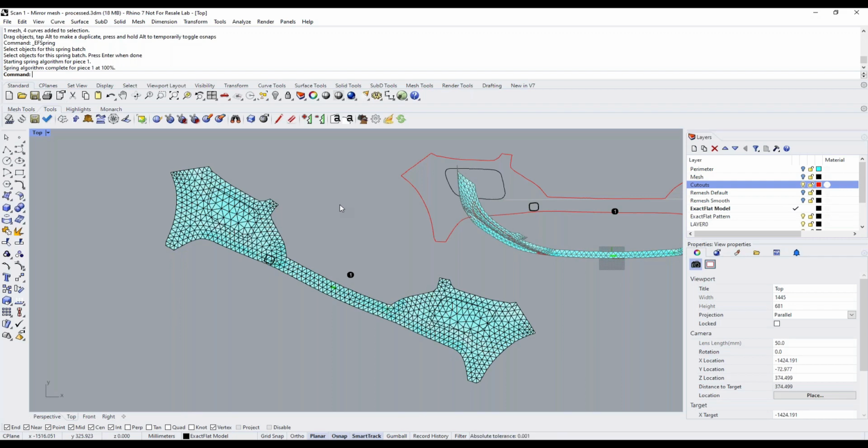Now, with respect to edits, I'm not sure what edits you're talking about. If you're talking Adobe Illustrator, and for example, if you're making edits like graphics and things like that, the graphic edits are not backwards compatible then into a DXF. You'd have to create your output file from Adobe Illustrator and then take it from there. We can make edits to the 2D file here, so you can put in a dart or a cutout in 2D. You can do the darts or cutouts in 3D, and in fact, they're usually done in 3D, and then they're automatically sized when you flatten the part.